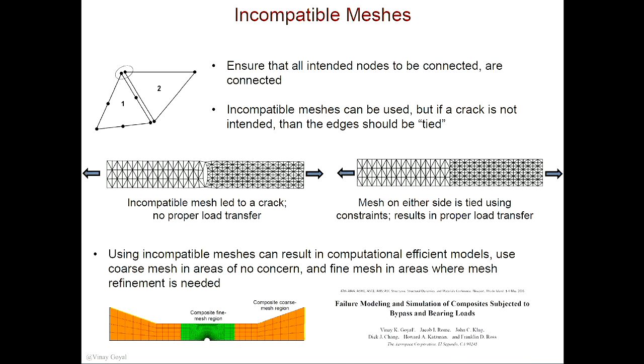Also, it's important to check that once you mesh everything, they have coincident nodes. Sometimes you can have elements that are disconnected. So you can actually equivalence the nodes to make sure that everything is glued together. You don't have nodes floating around, okay? So you want to make those checks with your models, okay?